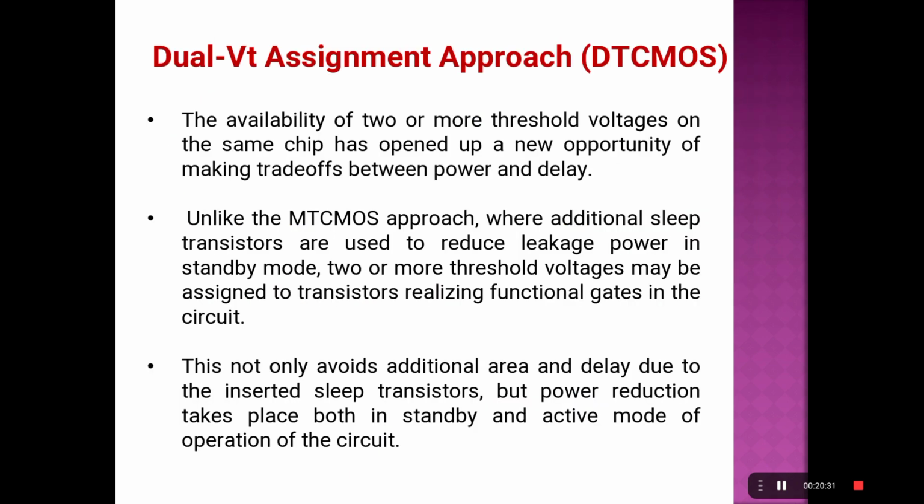Next, we will move on to the dual VT assignment approach. It is also one of the most important concepts. It is also called dual VT assignment, and we can also call it DTCMOS. The availability of two or more threshold voltages on the same chip opens up new opportunities for making the trade-off between power and delay.